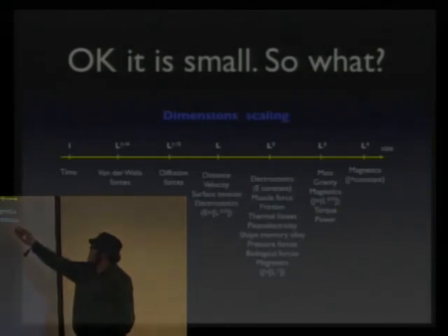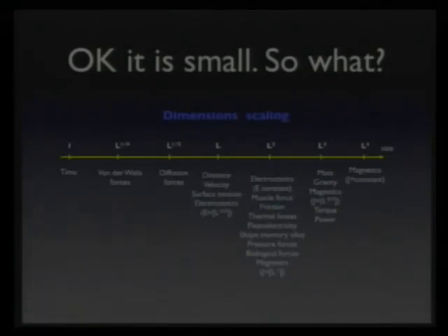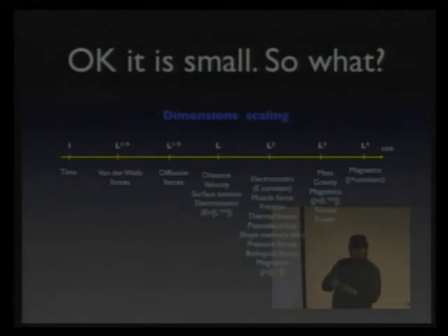Gravity and mass shrink with the power of 3, electrostatics with 2. This explains why you will find piezoelectric effects, and why you won't find a conventional DC motor on the microscale: the magnetic effect weakens so fast that when you get small enough, the electrostatic effect is bigger than the electromagnetic effect. That's what you always have to keep in mind.